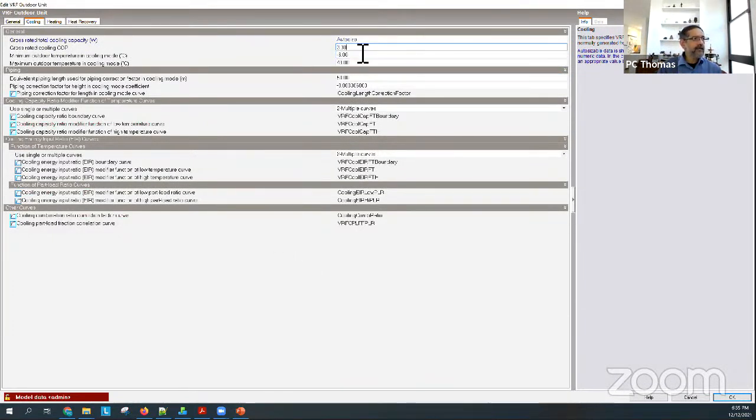The only number that I would suggest, if you have information, is you change this. If you don't have any information, leave it at that. Say that your system is 3.3 COP at design conditions. That's all you need. Okay.